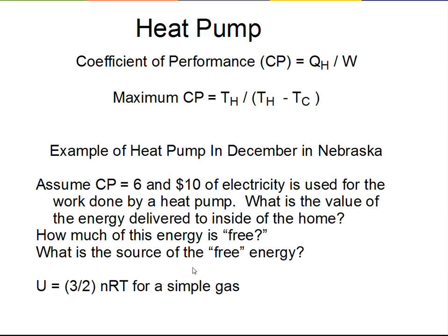So for minus 5 Celsius, we've got 268 here to put in for the temperature in Kelvin. Minus 5 plus 273 to convert to Kelvin. So 268 for the Kelvin temperature. The outside air in winter does contain energy, and heat pumps can extract that energy and deliver it to a home. So that's the mechanism of the heat pump.